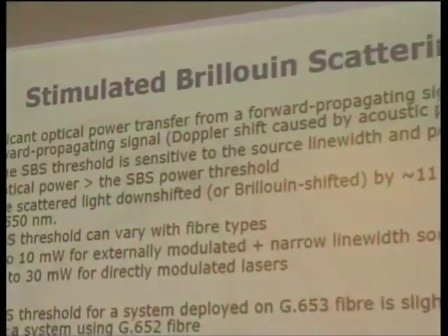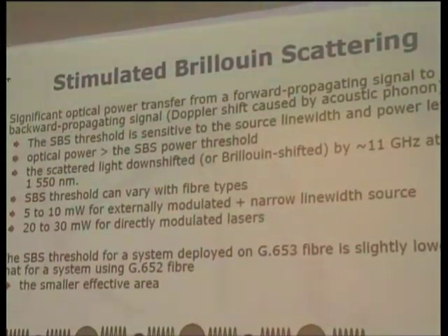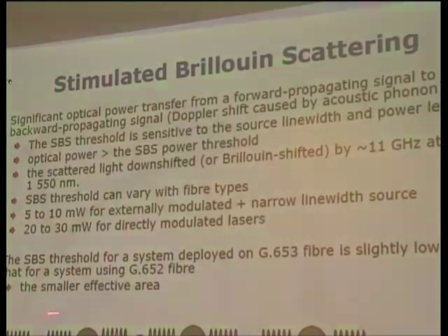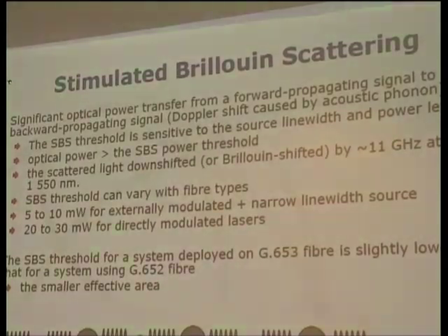Now I will describe stimulated Brillouin scattering. Have you heard of stimulated Brillouin scattering, or SBS, in a transmission system? This could be problematic when you input higher power to the transmitter for long distance transmission. It is caused by the molecular vibration of the glass fiber, so the glass itself. This is just a simple model of the vibration of a glass molecule.